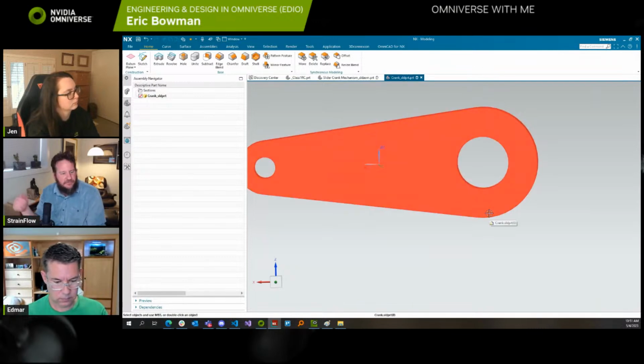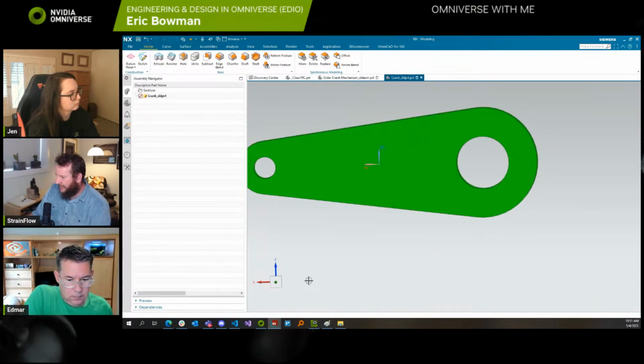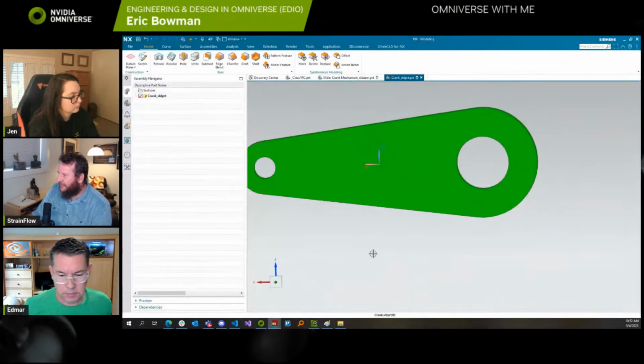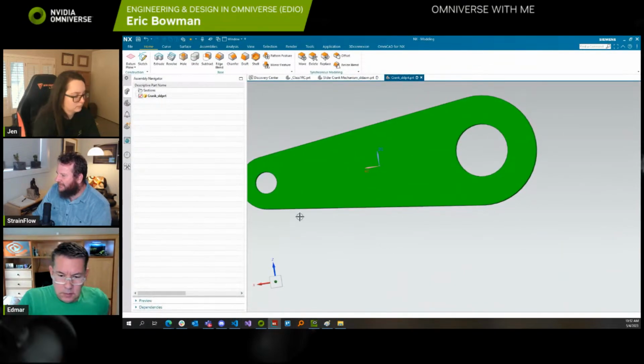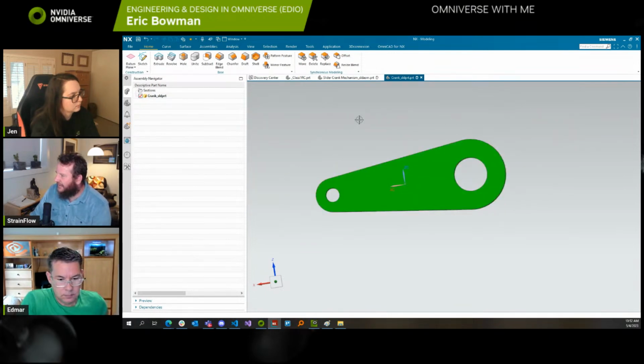You have to have those. You'll want to apply your boundary conditions, loads, and restraints to those non-design domains. So let's go back to this. You can see we've got those. This is our design domain. For us, we could actually start with this shape, but in my experience, if we let this bow out a little bit, it's going to come up with a more efficient design. So we'll probably make it even a little chunkier and let it go out a bit more. That'll be kind of fun.